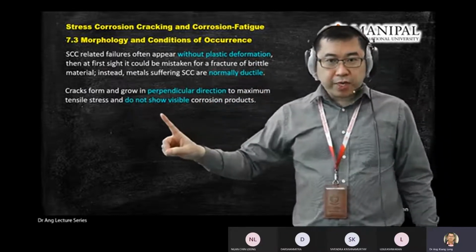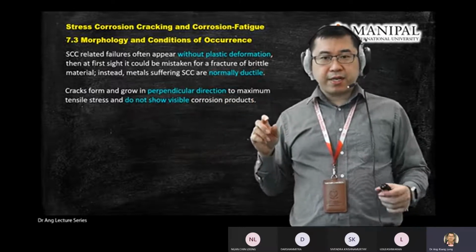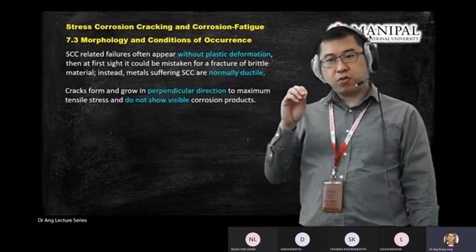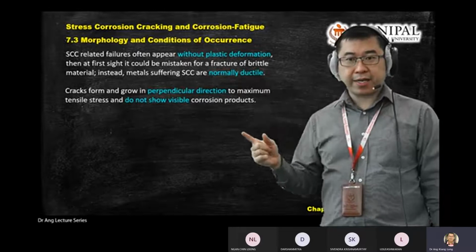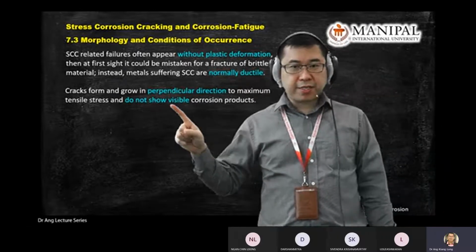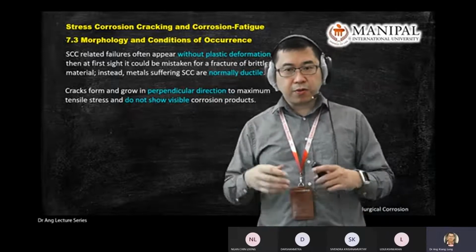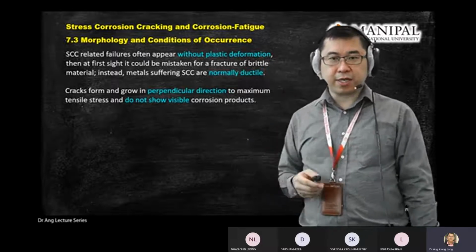And it does not show visible corrosion product. There's no product, no side effect like what you learned in the previous chapter. There's no oxide, there's no carbonate. But in SCC, straight away it creates a crack. It creates a canyon at that localized location.